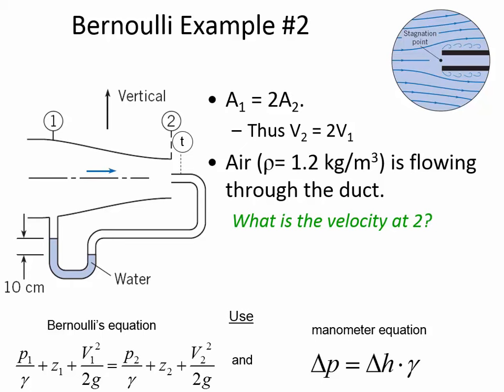That's right. The velocity of the air inside this tube is 0, because this manometer, remember we were doing manometers way back during the hydrostatic chapters, and so the fluid is not flowing through this manometer. So once the air gets into this tube, the conditions are static. So V sub T is 0.